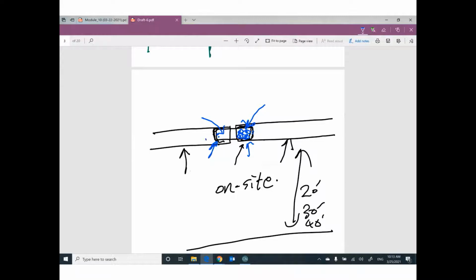Both of them, most of the time, are bolted. It's easier in construction and easier for maintenance. If you would like to remove this blade, you can release these bolts, remove the blade and replace it. But if you have one side bolted and one side welded, no way.